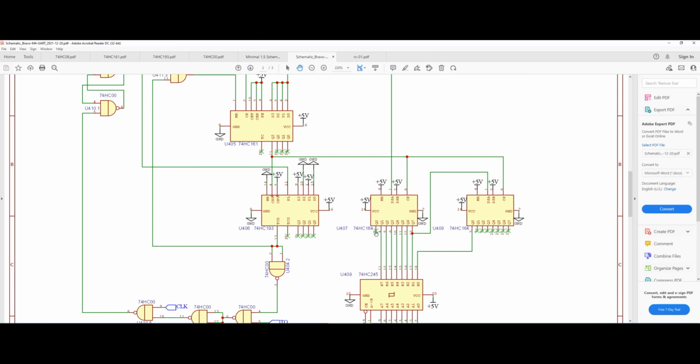And that's interesting because, as you can see, Q0 is not connected to our transceiver. It's not connected to our output. Therefore, we just ignore that. And that is normal. That is expected. We really don't care about that high bit at the end of the data, because this is not part of the data. The data is really 8 bits.